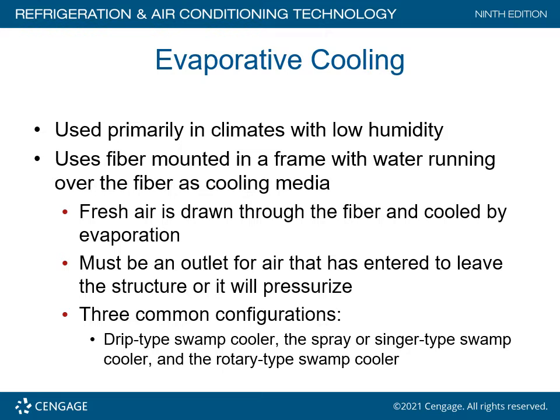The only problem with swamp coolers, or evaporative cooling as we call it right here, is that the air tends to be loaded up with moisture. Too much moisture can be very destructive, just as too little moisture can be. So that being said, one of the issues that I have is that you're dumping a lot of moisture into the air, and in some cases this creates problems with mold growth and some other issues.